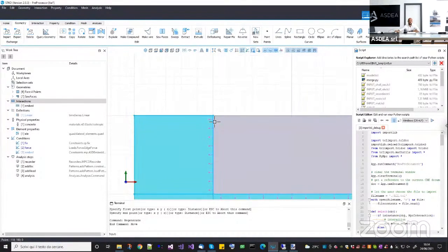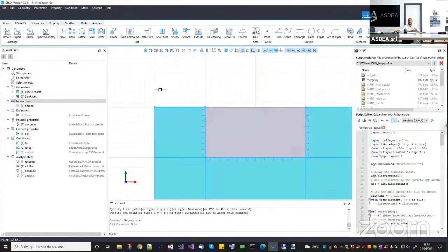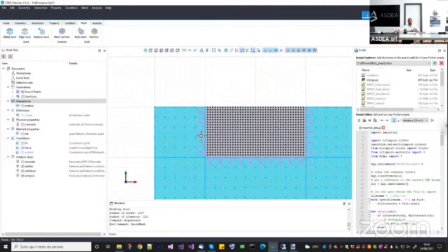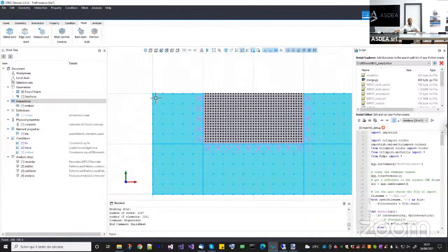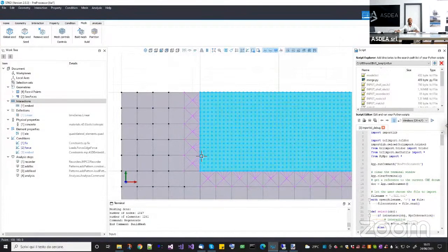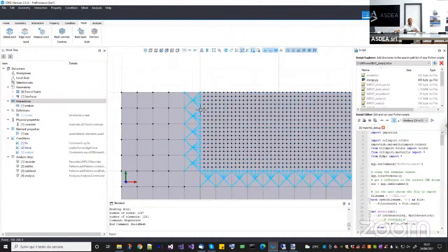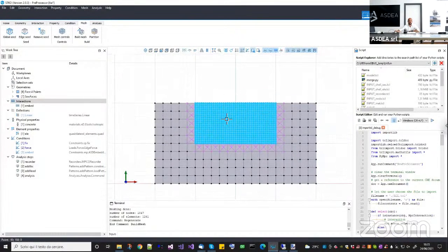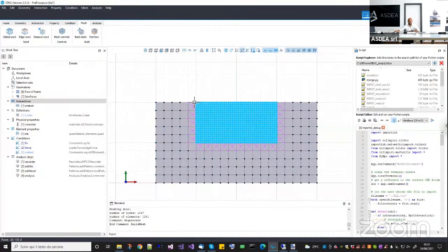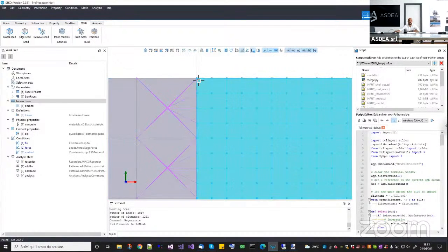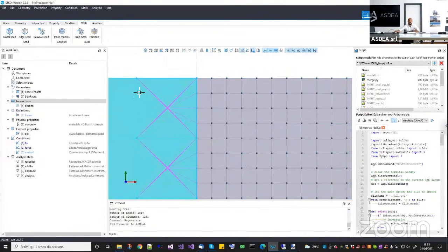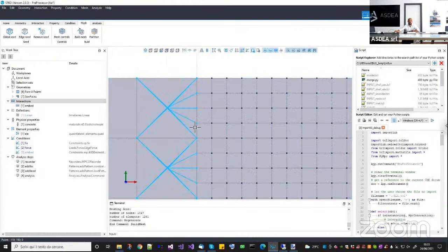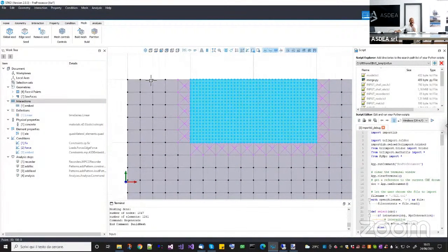Now you can see that every point of the edge is connected to the nearest point of the face. And if I do a mesh, I already prepared a mesh that has a global seed of 10, and here I used an edge seed, which is much denser, like 5 or 0.05, I don't remember the number, but it is much denser. Now, as you can see, each and every node here on the border is connected to the nearest element. So this node will be connected to this element, this node to the other elements, this node in the middle, and so on. Now let's see what happens.